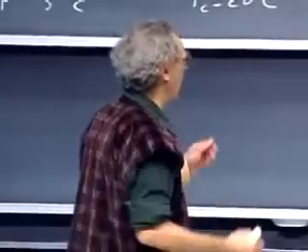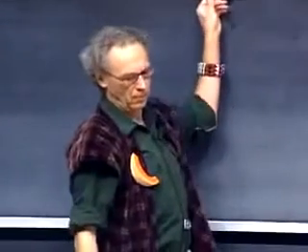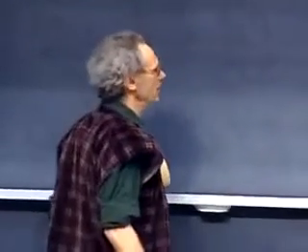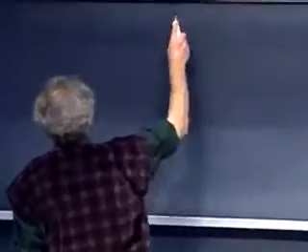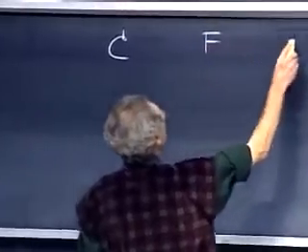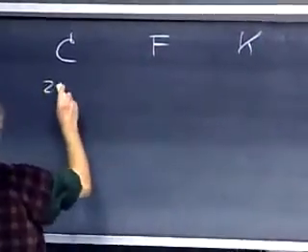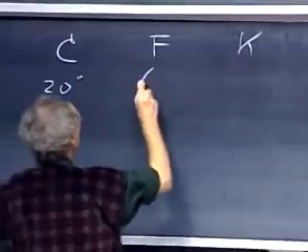And so we now have a third scale, which was introduced by Lord Kelvin, who's a British scientist. He did a lot of research on heat, and he introduced the absolute scale, whereby he uses the lowest possible temperature as 0 degrees Kelvin. But the increments, in terms of increase of 1 degree, he uses the same as the Celsius scale. So an increase of 2 or 3 degrees Kelvin is the same as an increase of 2 or 3 degrees centigrade.